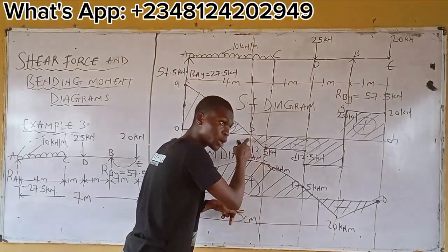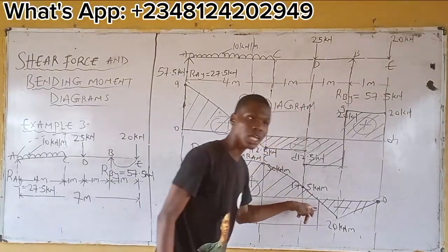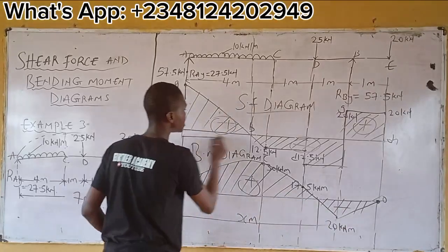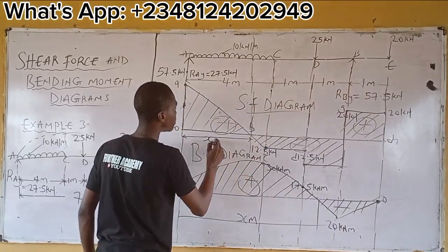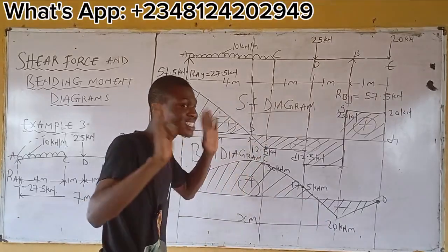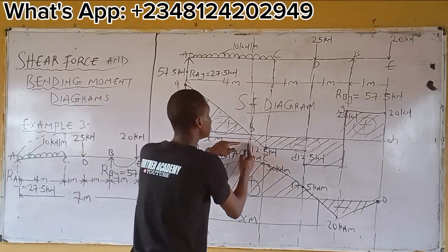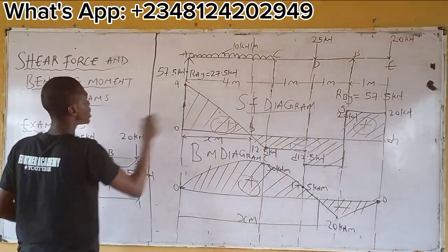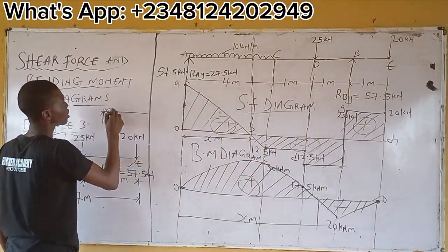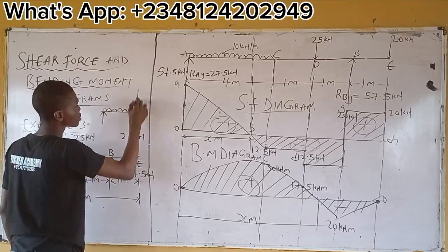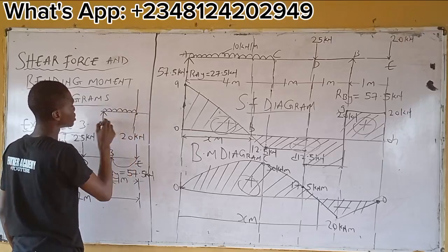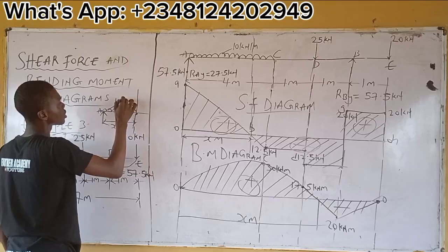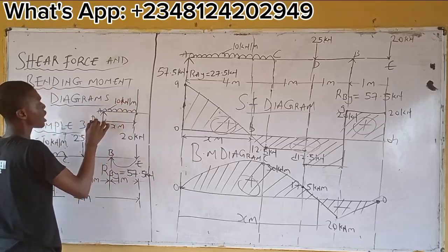This is a maximum bending moment, right? This is point of contraflexion. Now, we want to get the value of x. This is the x for point of contraflexion, and this is the x for maximum bending moment. So now, as the name implies, you are going to section this beam as well. After sectioning for this guy, you'll be left with something like this, right? I've sectioned. We don't know this point, say x meter. This is A, this is 10 kilonewton per meter. This is R AY.